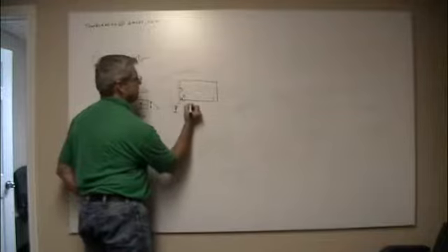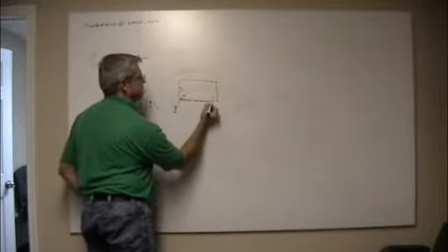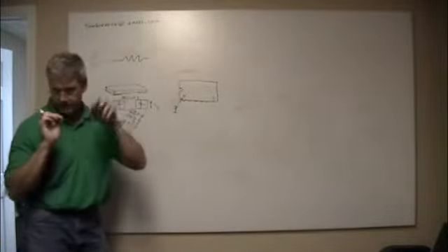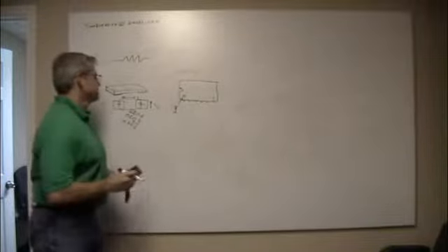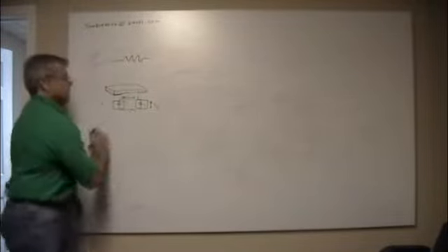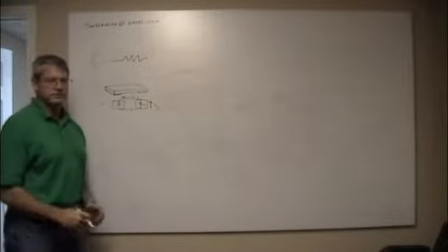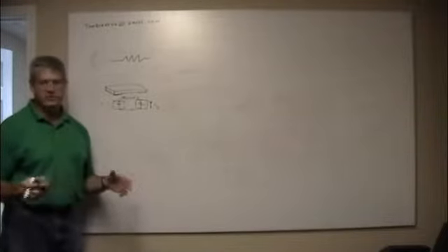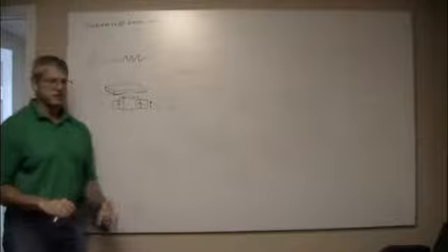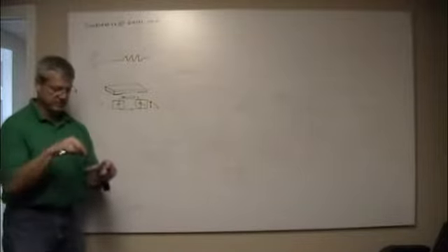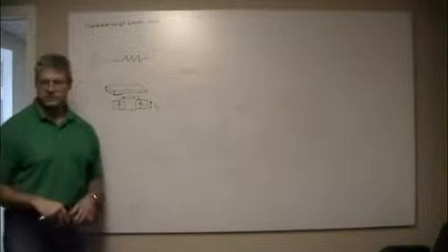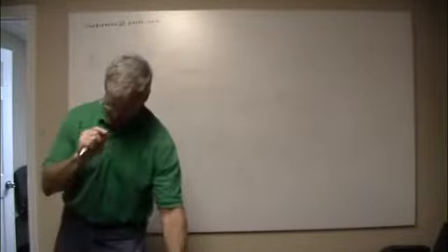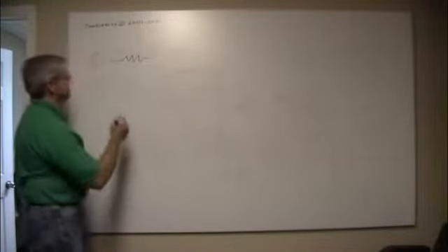And the leads basically come down right here on the sides and go down through the board. Easy to solder. You put the soldering iron on the back side. Done. Surface mount stuff, you usually use a solder paste, and then it goes in an oven. Personally, I took a toaster oven, ripped it apart, put a process controller in it, and I can put my board together, you smear your stuff all over and place your part, stick it in there, hit the button. 5 minutes later, I've got a circuit board that's completely soldered. Then I spend a lot of time doing touch-up because I put too much solder paste down and it balled up into a mess.